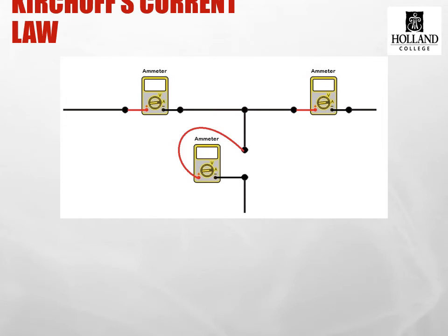So now we've looked at the basic tenets for parallel circuits. Voltage is common, currents add, resistance adds inversely, or a reciprocal sum, and powers add.